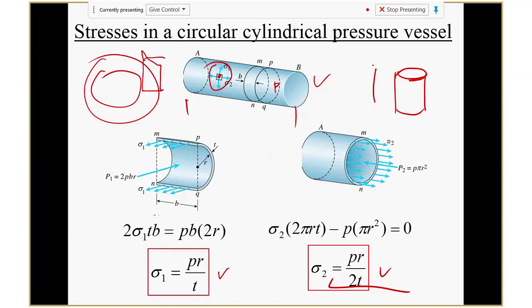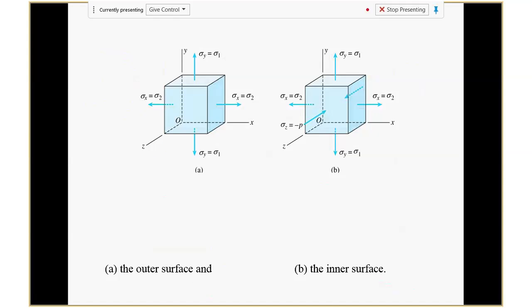Okay, so then I ask you to see if you can draw the Mohr circle, determining the principal stresses and the shear stress. Anyone try? No? You should try homework, right? Okay, all right, let's do it together then.